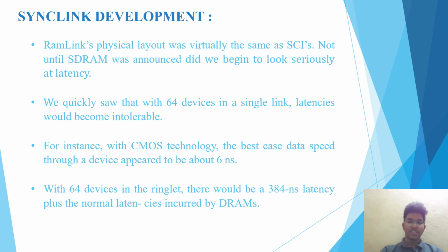We quickly saw that with 64 devices in a single link, latencies would become intolerable. For instance, with CMOS technology, the best case data speed through a device appeared to be about 6 ns. With 64 devices in the ringlet, there would be a 384 ns latency, plus the latencies incurred by the DRAMs.